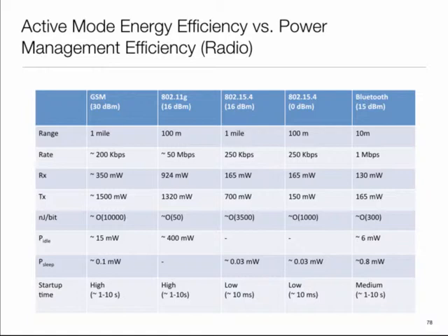So a couple of things are happening. Firstly, the Wi-Fi devices are complicated devices, just in terms of how many transistors they have. All this high-speed stuff comes because the electronics are more complicated. So they have lots of leakage power. Good old equation. So that's why the idle power is much higher. Whereas Bluetooth radios are very simple radios, with fewer transistors, so that's the effect you are seeing. These Zigbee radios were, interestingly, explicitly designed to be rapid to wake up.